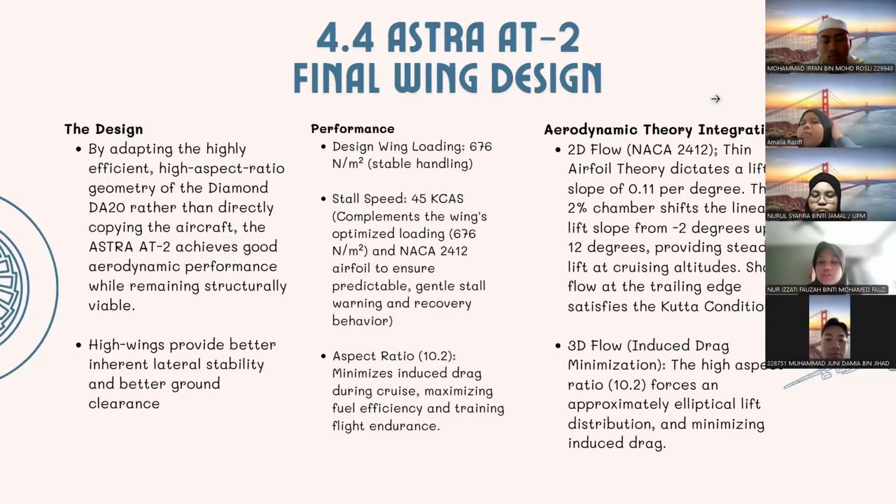Hi, my name is Nuralya Fauzah binti Muhammad Fauzi. So I'll be explaining about the final wing design. So the design we adapt from the DA20. So it achieves good aerodynamic performance while remaining structurally viable. So the high wing provides better inherent lateral stability and better ground clearance. So the aspect ratio minimizes the induced drag during cruise, maximizing fuel efficiency and also training flight endurance.